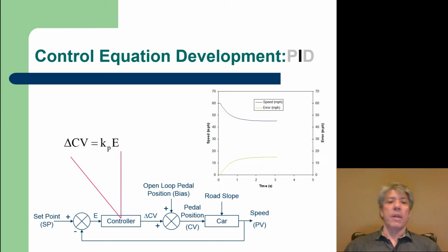Another thing that can happen if you increase the proportional gain too much is it'll make the pedal, in our analogy, slam all the way down. That'll make the engine go too high power output, which will make us go too fast. And then with too high proportional gain, the pedal, once we're going too fast, will go all the way back to nothing and try to get the engine to output 0 power, which means that we'll go too slow. And so we'll have this constant oscillation. And really that's on-off control, but we'll talk about that a little bit later.